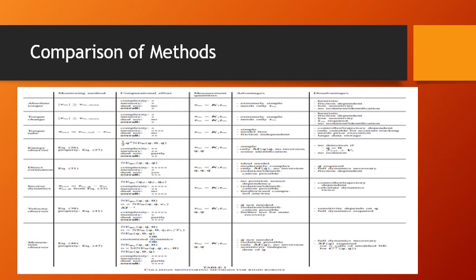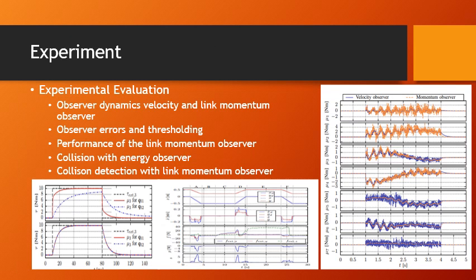On the other hand, the two monitoring schemes based on velocity and momentum observation emerge with the following major advantages. One, simultaneous collision detection, isolation, and identification, and second, a complete impedance form with reference trajectory and control law in execution. They are the best methods to solve the context-independent phases of the collision pipeline for both rigid and flexible robots. Experimental evaluations have been discussed in each section.